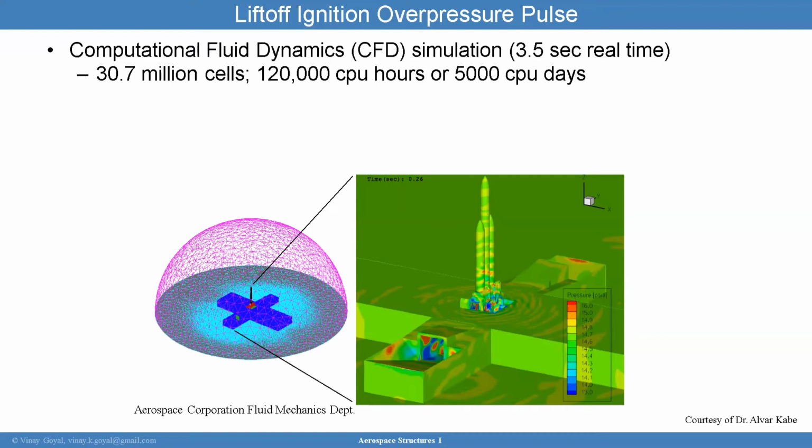But the chamber pressure is usually just enough to choke the throat, so you get a strong normal shock that forms at the beginning of the diverging nozzle. When a shock is formed, the first significant pressure wave will propagate out of the nozzle and then up the vehicle as well as down through a launch duct. So that's very important to really consider.